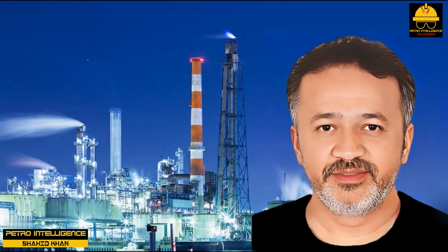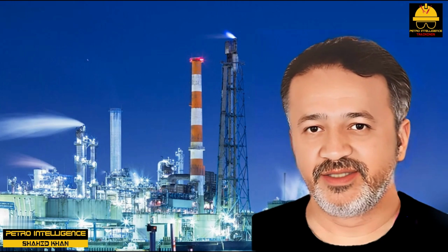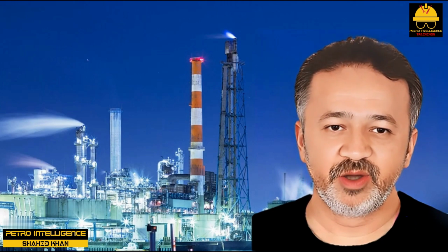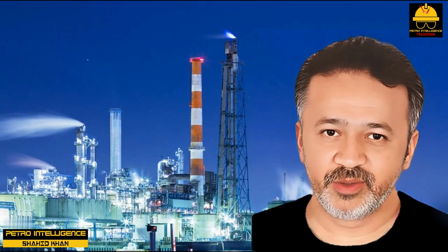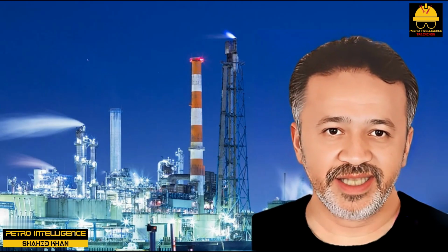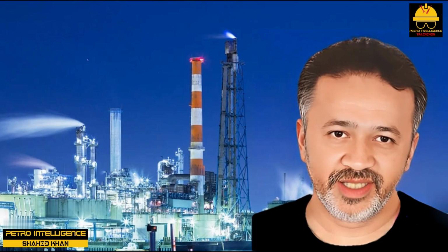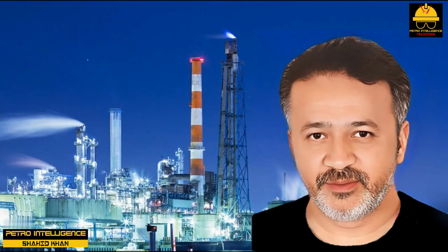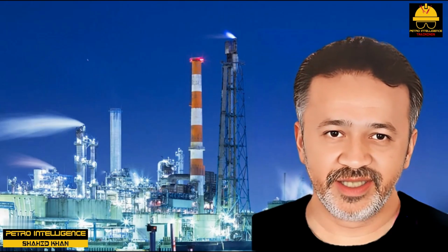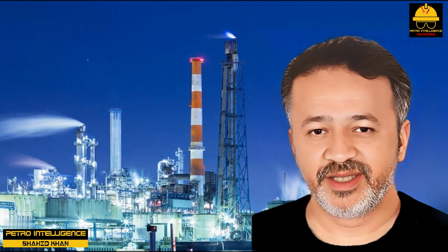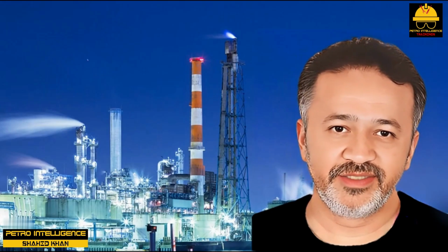Refrigerant composition. A very large percentage of refrigeration systems are not limited by the compressor driver horsepower, the condenser, or the evaporator. Many refrigeration systems are limited by either compressor suction volume limits, the mechanical pressure rating of the compressor case, or the refrigerant condenser shell.